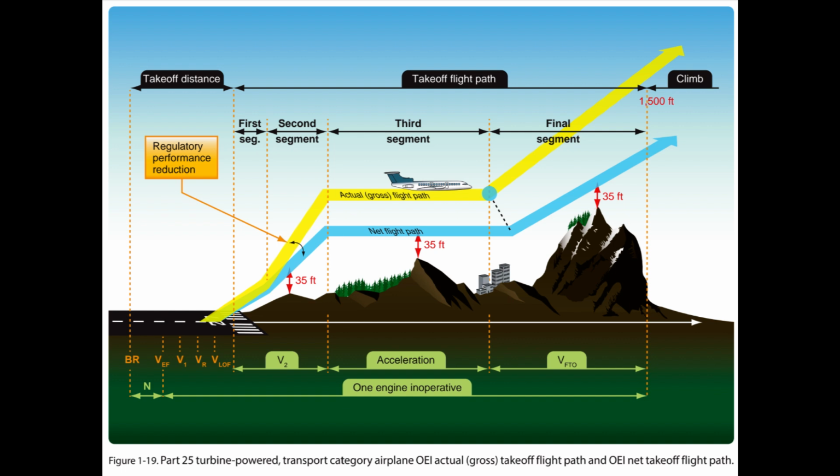Advisory Circular AC 120-91, Airport Obstacle Analysis, provides guidance and acceptable criteria for use in determining the safe lateral clearance from obstacles when developing takeoff and initial climb-out airport obstacle analyses and engine-out obstacle avoidance procedures to comply with the intent of these regulatory requirements. Pilots departing an airport under IFR and operating under Part 121 or 135 are required by 14 CFR 91.175(f)(4) to use an engine-inoperative takeoff obstacle clearance or avoidance procedure that assures compliance with the obstacle clearance requirements, Subpart I, of those rules.